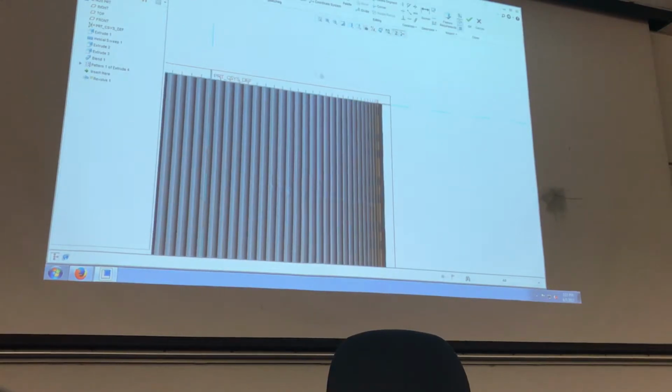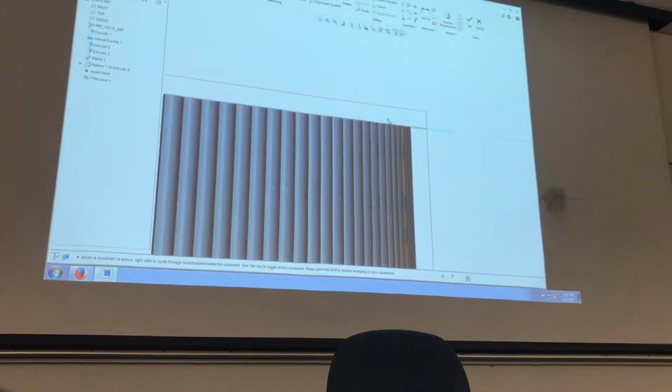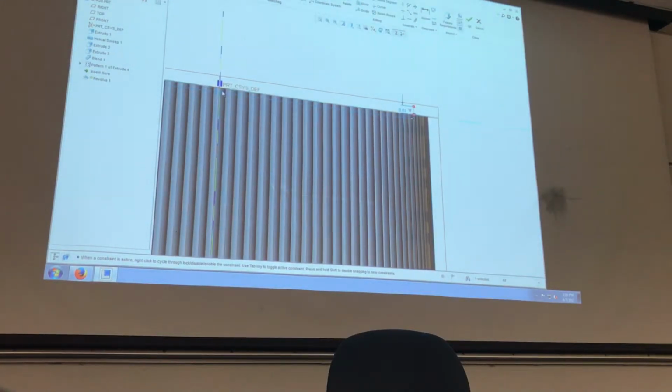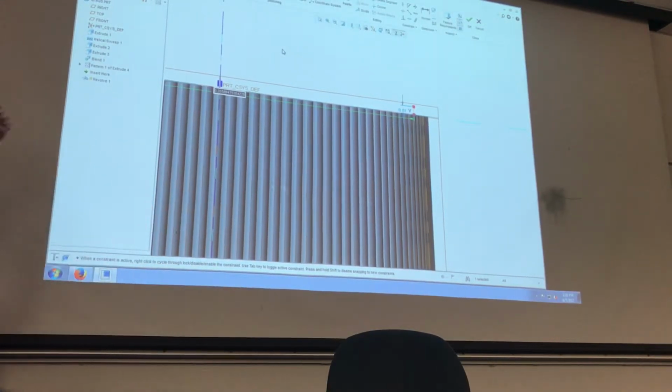What that's going to do is allow me to go ahead and snap to something. So I'm going to use a center line here to here. I'm going to go ahead and use a line vertical initially. The only reason I'm doing this is so I can set this distance here. Okay. My inside diameter was 0.375. So this needs to be something slightly less than or at 0.375. Otherwise, it's not going to intersect with everything. It's going to create issues for me. So I'm just going to set it at 0.37. Should work.